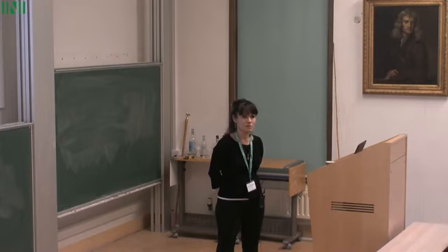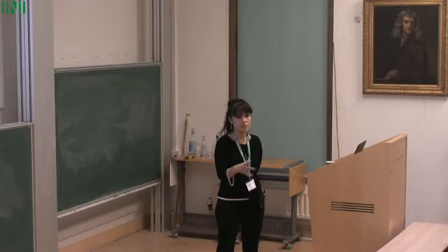On a related note, those models are based on the small strain approximation, right? Yes. Is there a chance or hope to go beyond that? I don't know. You can try to put non-linear elastic energy in that model. In that case, of course, you have to be very careful differentiating between your deformed state and undeformed state.